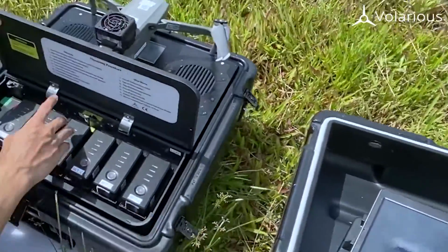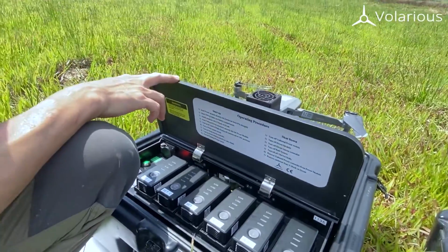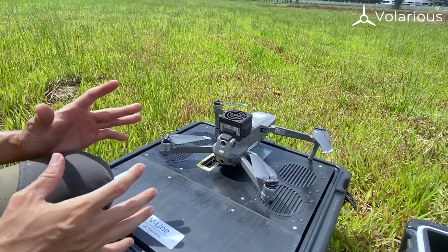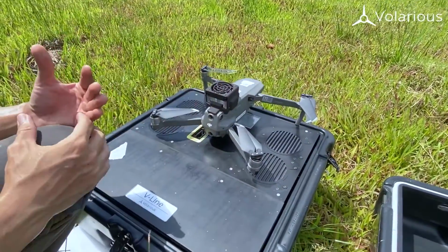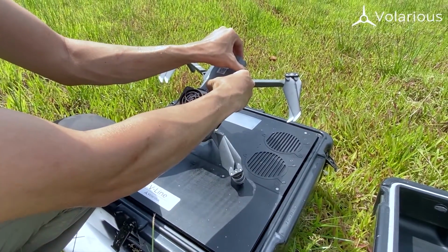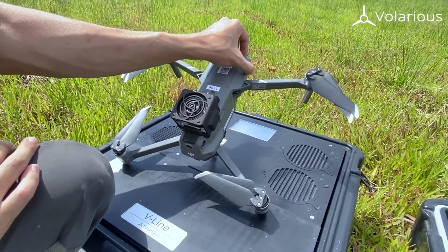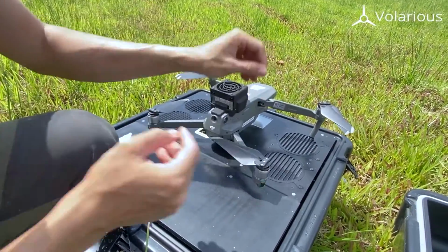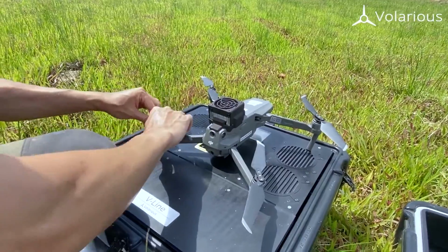Next, step number 8, I will turn on the power module, which is this backup battery on top of the drone. This is to ensure that the backup battery will be online, just in case anything happens to the V-Line set. The backup battery on the drone will kick in to supply emergency voltage. So I will power on the backup battery, and you can observe that the fan starts spinning, the drone comes online. It's also good practice to unfold all the propellers before you fly.